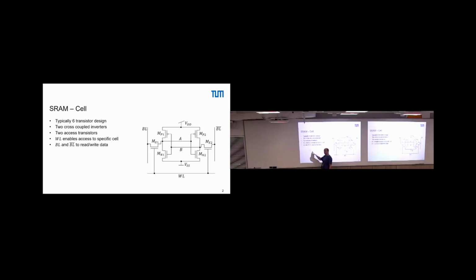So our inner voltage goes down, because it's just a voltage divider then. We have a resistor here, we have a resistor here. The higher the voltage at the input, the higher the resistance of this transistor, the lower the resistance of this transistor. So the voltage at this point decreases. That's what we have in this part. And at some point, this transistor here is fully conducting. This one here is fully non-conducting, there's no channel anymore. So we are at the output at ground.